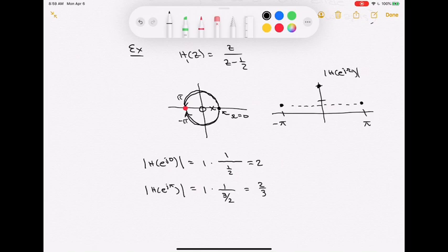Same point in there. And if you look at this, in fact, because of the symmetry about this horizontal axis, we know that the magnitude response, all the distances there, have the same symmetry across that horizontal axis. If I flip this guy top from bottom, it's the same. I'm going to get an even magnitude response, just like I did in continuous time. Real systems, those that have roots that come in conjugate pairs, will have the symmetry necessary so that the magnitude response is even.